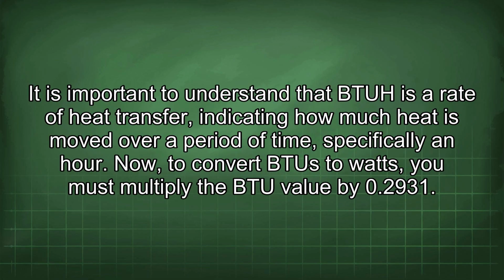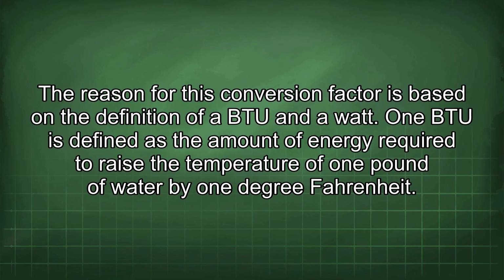It is important to understand that BTU/h is a rate of heat transfer, indicating how much heat is moved over a period of time, specifically an hour. Now, to convert BTU to watts, you must multiply the BTU value by 0.2931. The reason for this conversion factor is based on the definition of a BTU and a watt.